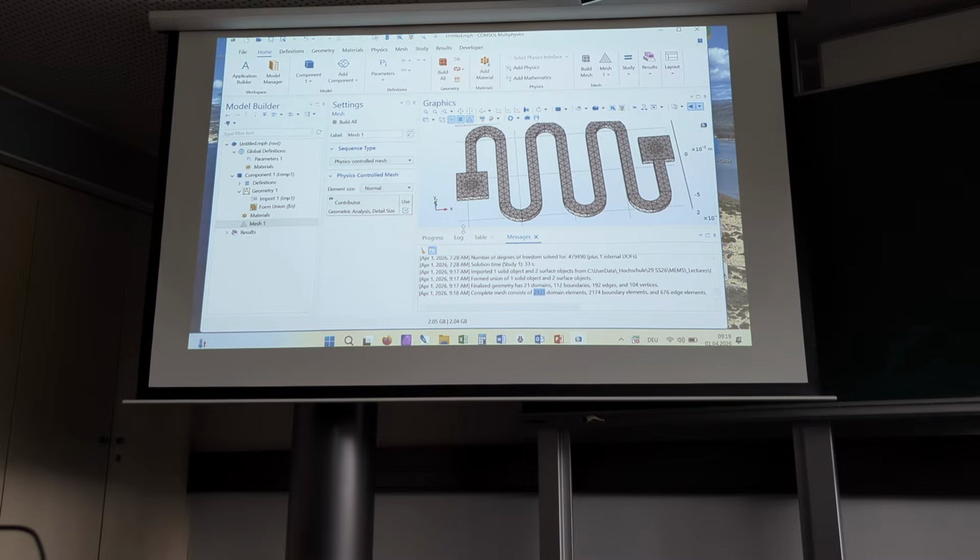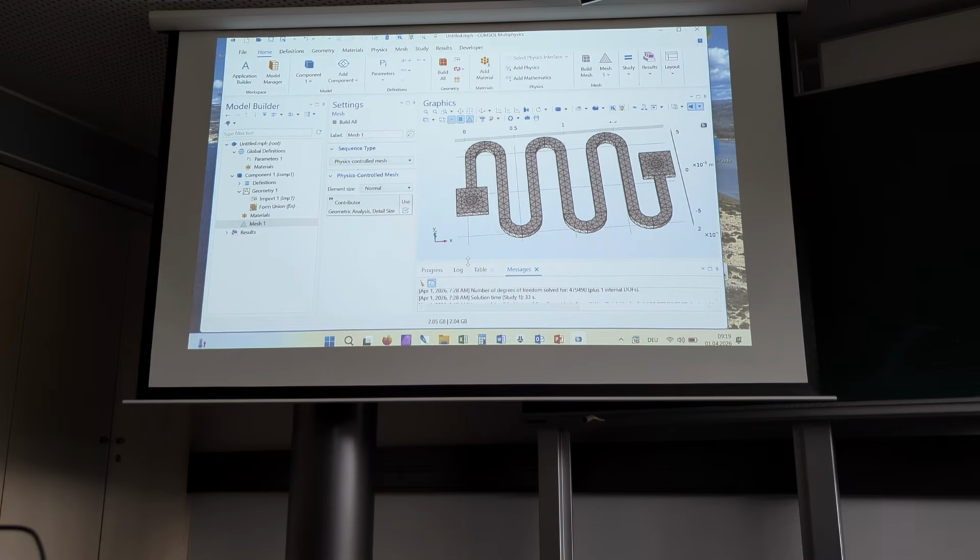So that wouldn't be critical. 3,000 elements is certainly not a problem, but it's just an example. If that would be a problem, the strategy would be to save mesh elements by using here a structured mesh generated with the swept operation.